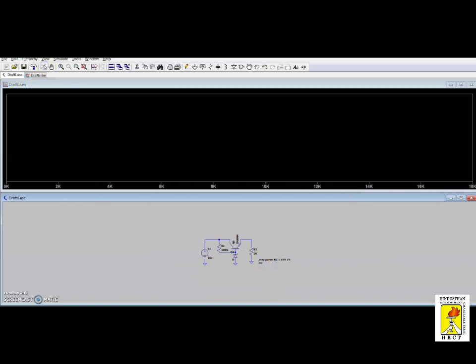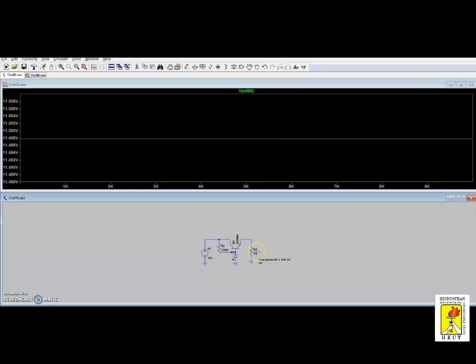You get it like this. Now you can look at the difference: in the x-axis we changed the resistor values 1K, 2K up to 9K, in increments of 1K up to 10K. For load regulation, we have to change the load resistance, so we sweep the load resistance from 1K to 10K while keeping the input voltage at 16 volt. Now I am going to measure the output voltage across the load resistance, so I keep my voltmeter over here. For 16 volt input, I am getting a regulated voltage of nearly 11.5 volt.